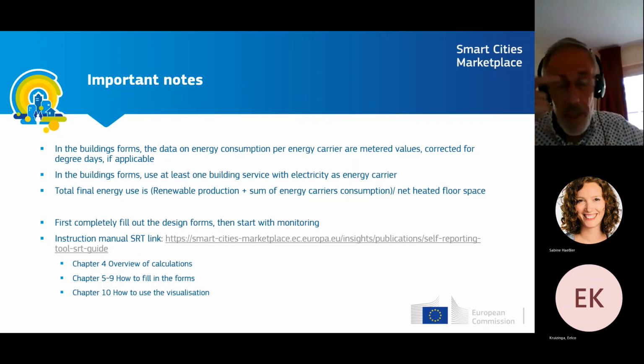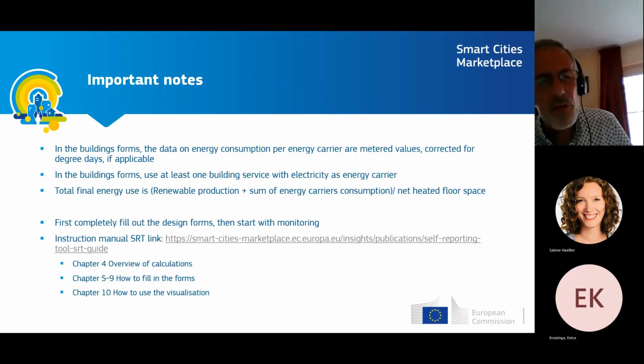When it comes to using the system, I think a few things are important. Please be aware of the fact that data on energy consumption are supposed to be metered values, corrected for degree days. So that's something that you need to do yourself. And when creating building forms, it's necessary to create at least one building service with electricity as energy carrier. We do not suppose that there are any buildings without electricity connections nowadays that are subject to these European projects. And also be aware of the definition of the total final energy use.